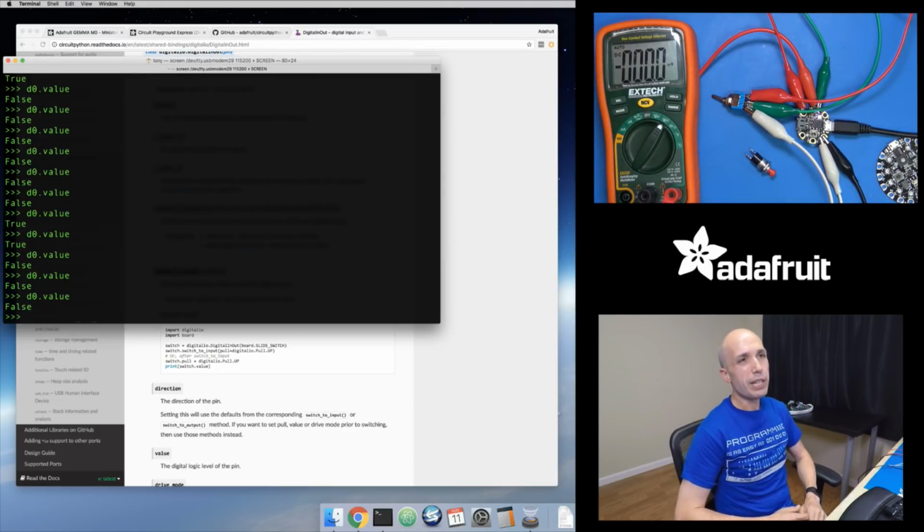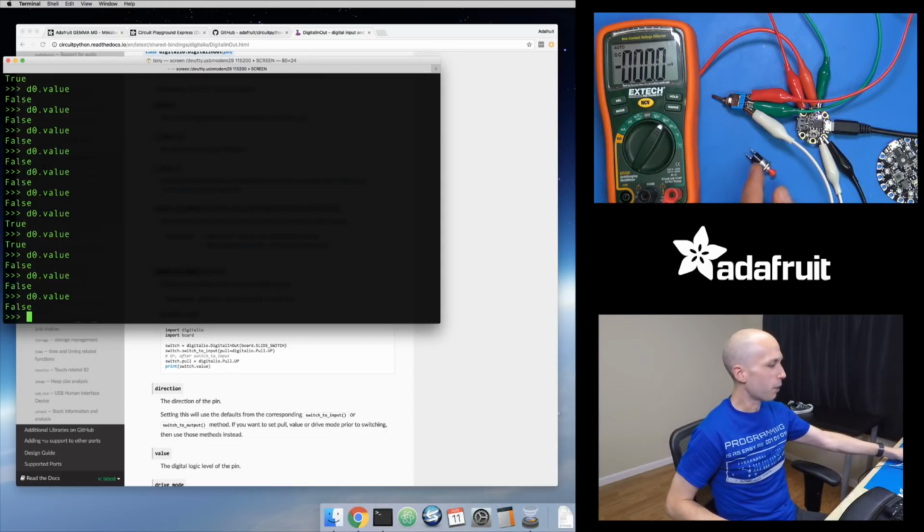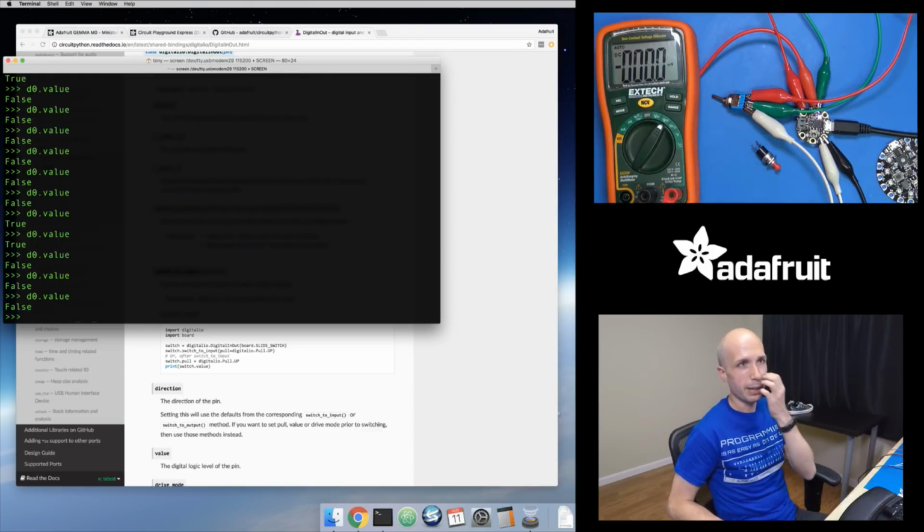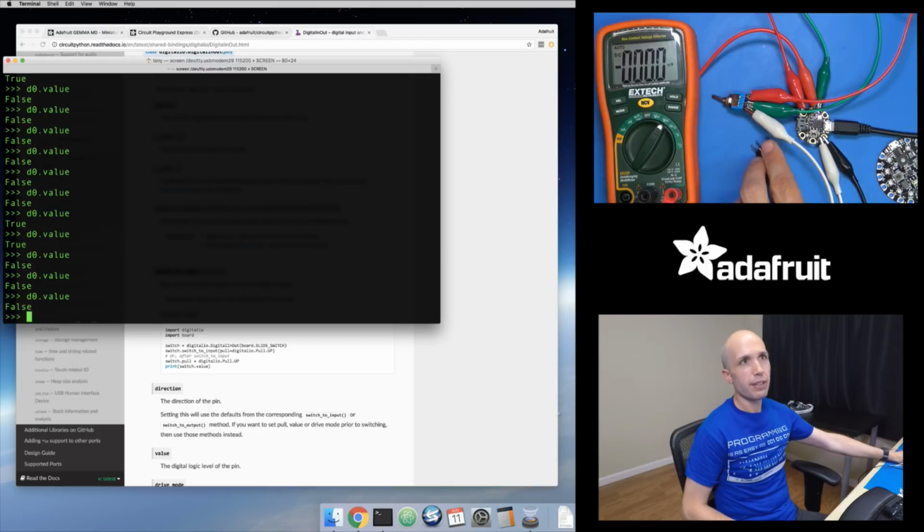Anyways, we can fix that floating issue, because for a digital input, I can add a resistor to it, a very low current resistor. So it's not strong. It's not going to override a stronger signal. For example, if I connect 3.3 volts to this, it's going to be a small enough resistor that it's not going to override whatever real thing might be connected to this. But with a resistor connected, when nothing is pressed, that input is going to go to some logic level.